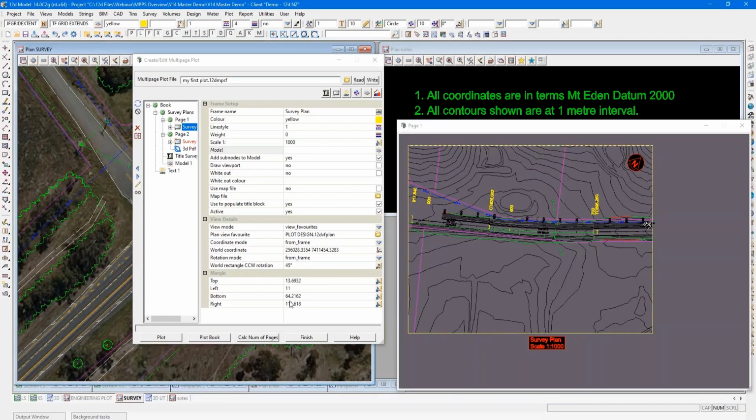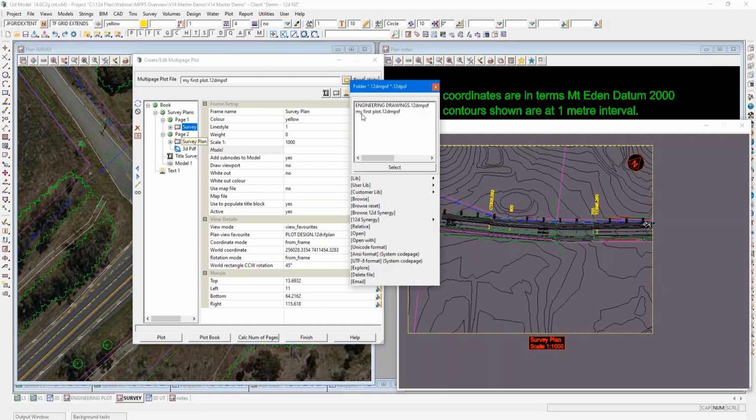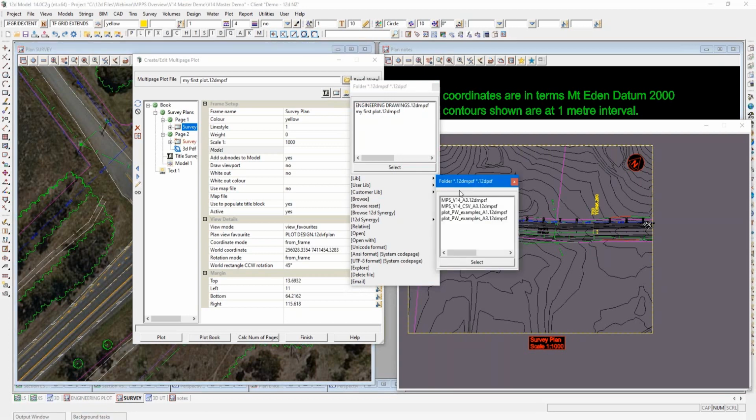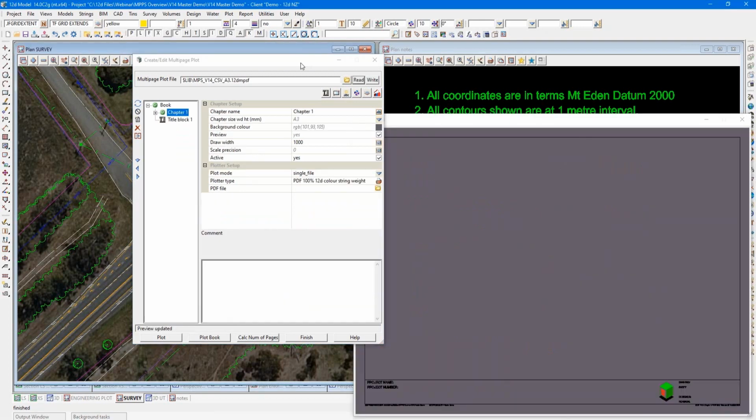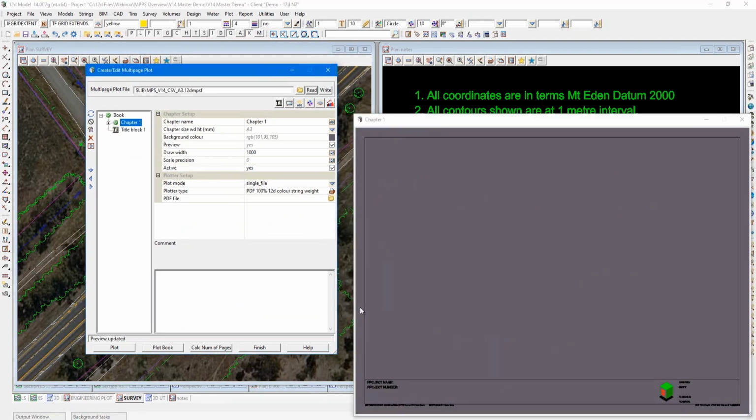Okay, no problem. I'll email these through to you as well. Great. I'll follow that up. And so Phil has asked, can you use formulas inside a CSV file to concatenate values? Yes, absolutely. We do have some clever things for that as well, but if you've got a drawing register, it is literally just populating the data from the particular nominated column inside the CSV file. So the answer to that would be yes, whatever is in the CSV file column in the cell will be what is populated onto the MPS page.